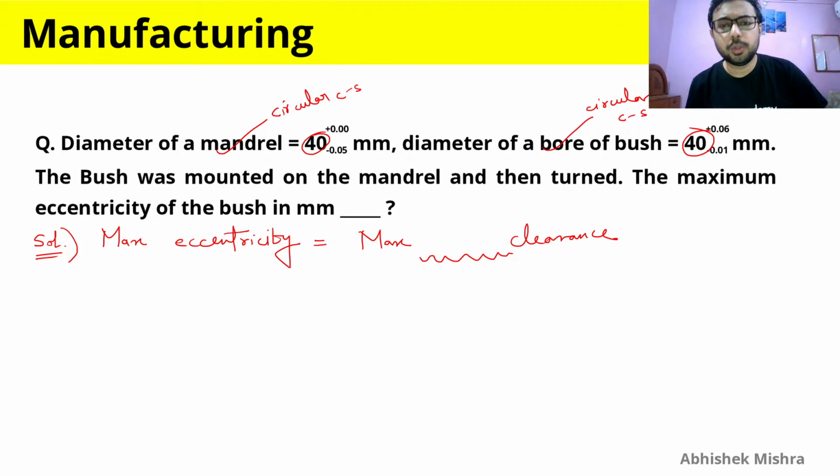the point of making you do this question is this gap here, this fill in the blanks here. Here it is radial. So just remember here that maximum radial clearance is maximum eccentricity. So you have to find the eccentricity, or you can find the clearance, but that clearance will not be the final answer, because maximum eccentricity is maximum radial clearance. Therefore you have to divide that maximum clearance by 2. And now maximum radial clearance. So first we will find maximum clearance, or let us just find it here only.